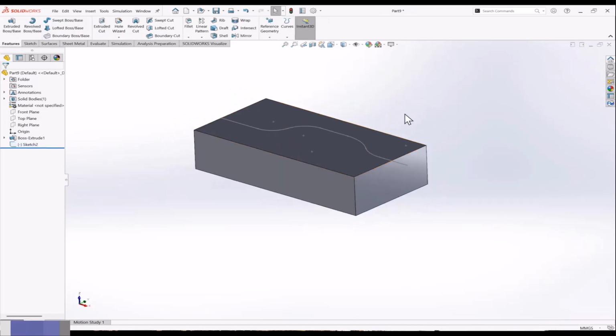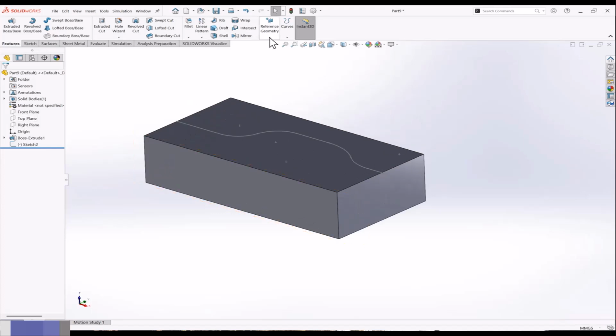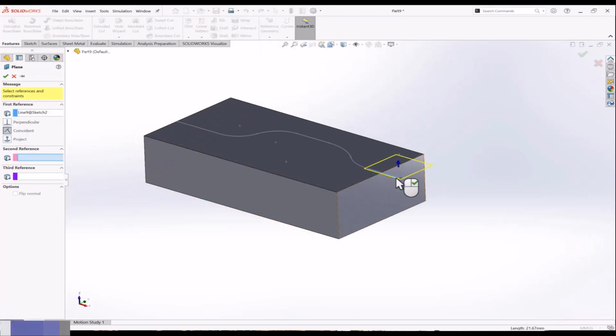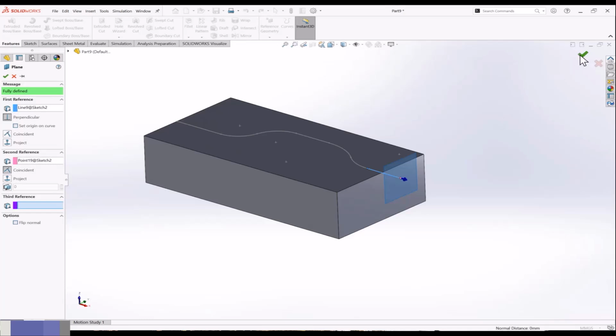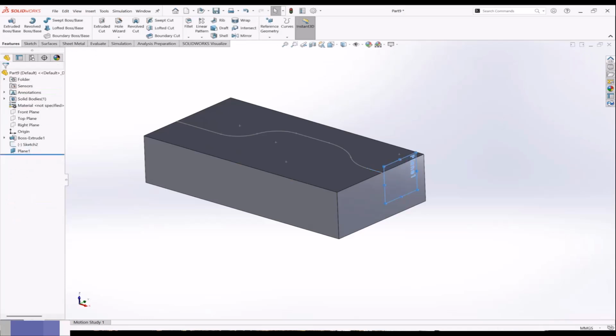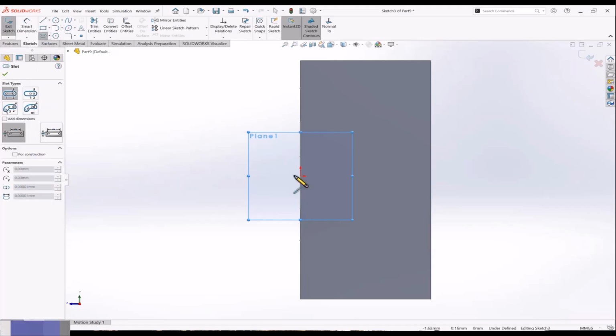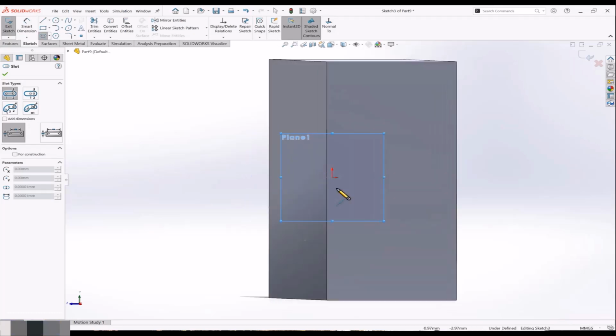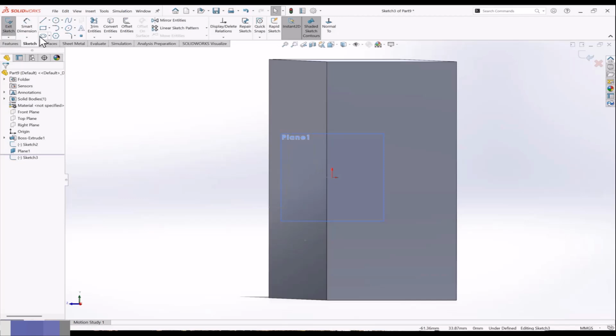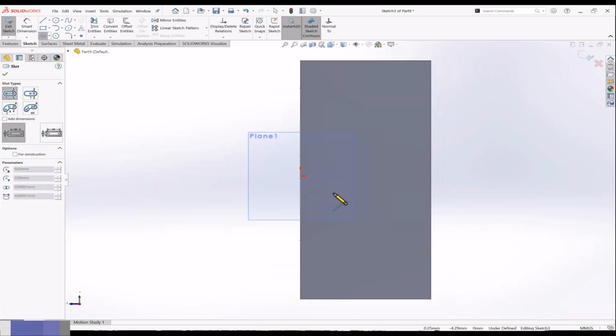You can make inside the body also by using planes. So I'll just use this part and do okay. And I'm going to make a cross section for how I want to cut it. So I'll just define my section. I want to cut the part. Let's take a slot. It's a side slot now. So let's make it.